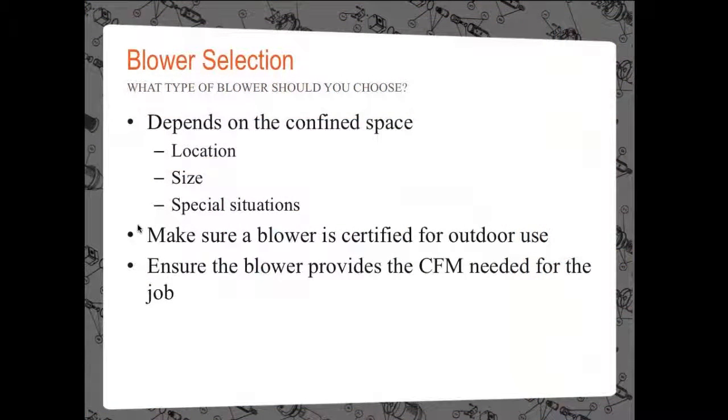Now that we understand the basics of confined space ventilation, let's discuss the most commonly asked question. What type of blower should you use? The answer will depend upon the confined space. Let me explain why. There are so many confined space situations, locations, sizes, and other variables that there's no one-size-fits-all solution. The first thing to consider is the blower certified for its intended use. For example, if it's going to be used outdoors, is it approved for outdoor use? Surprisingly, not all blowers are.